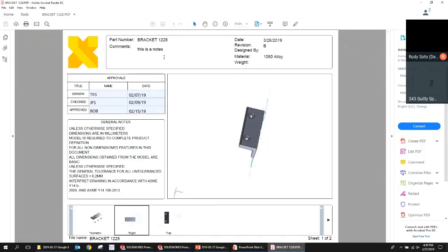And this is a big part of what the SolidWorks MBD add-in accomplishes for you, is allowing you to set up these templates the way that works appropriately for the type of project as well as for the department, and also outputting to different frames. Sometimes you have multiple frames. You'll see today as we go through some of the examples, we'll have multiple frames that each have a different view, things like that.